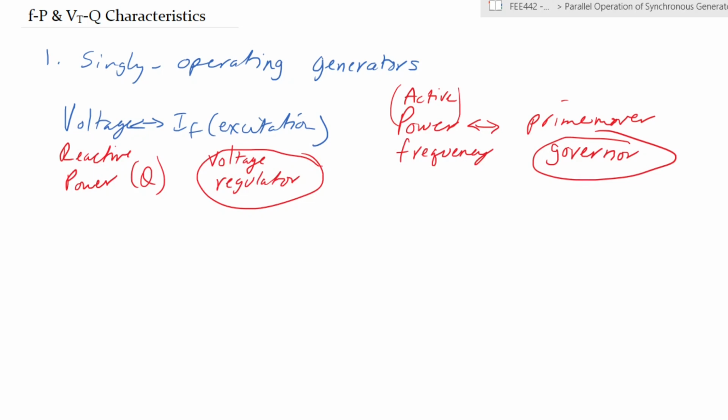Oh, I've just seen there's a question. How bright or how dim is the gauging, say if you're new to the equipment? Yeah, I think I mentioned that the problem would be, unless somebody had experience, it would be difficult for a layman to see straight off what the lamps are doing, or to identify what the significance of the brightness of the lamps would be. Yeah, which is why there's now the improved use of synchroscopes.